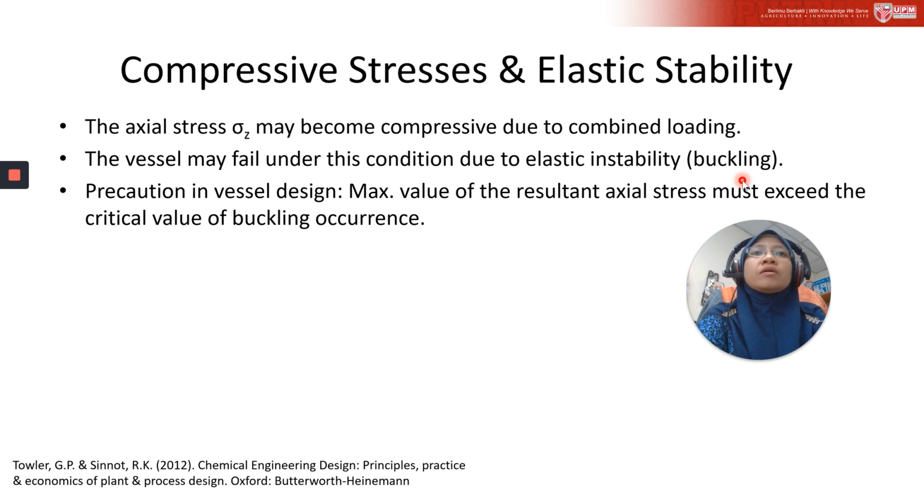So for this, there is a precaution in vessel design where the maximum value of the resultant axial stress must not exceed the critical value of buckling occurrence.